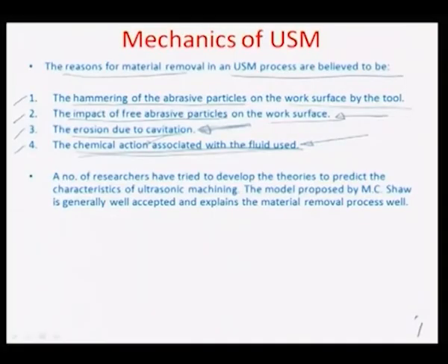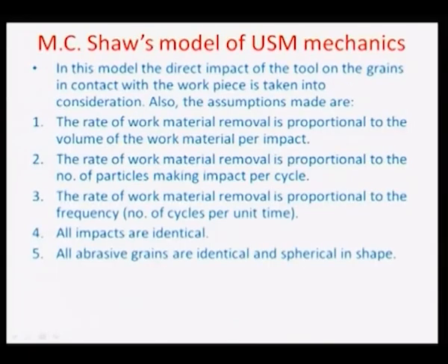So let us see some of the assumptions made by the Shaw model, as illustrated in the next slide. In this model, the direct impact of the tool on the grains in contact with the workpiece is taken into consideration,